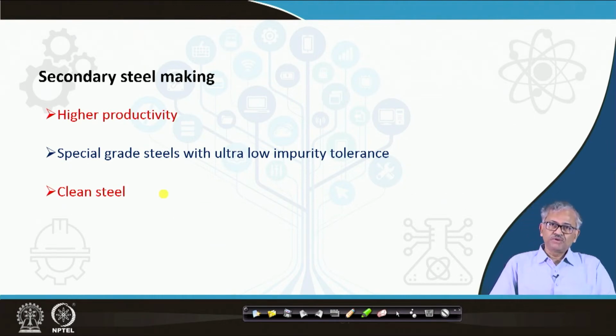So you can modify them to a certain size and shape distribution, with a certain shape, such that it doesn't cause difficulties in further processing of the steel. So that is called inclusion modification. Those inclusions cannot be removed, but they can be modified to a favorable size and shape distribution. That can be done, and that is called clean steel.